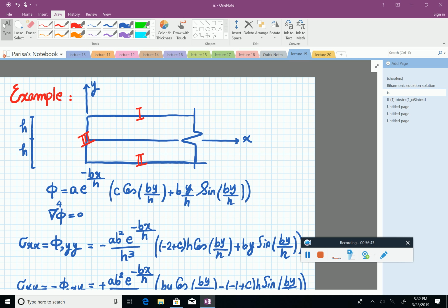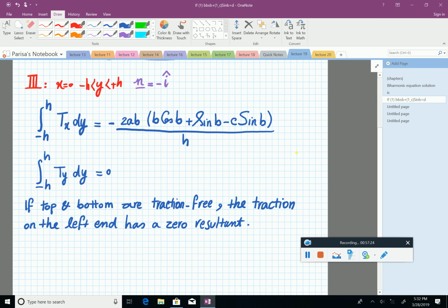This is a general problem with Airy stress function solutions. It's hard for students to understand because what you are used to is getting a problem with forces on it and then getting a solution. Here you get a domain and a stress potential. That's the best physical meaning I can think of for the Airy stress function. And then you try to find the problem that you can solve in that domain with that solution. It's kind of strange, but it's like a differential equation. You never question that.